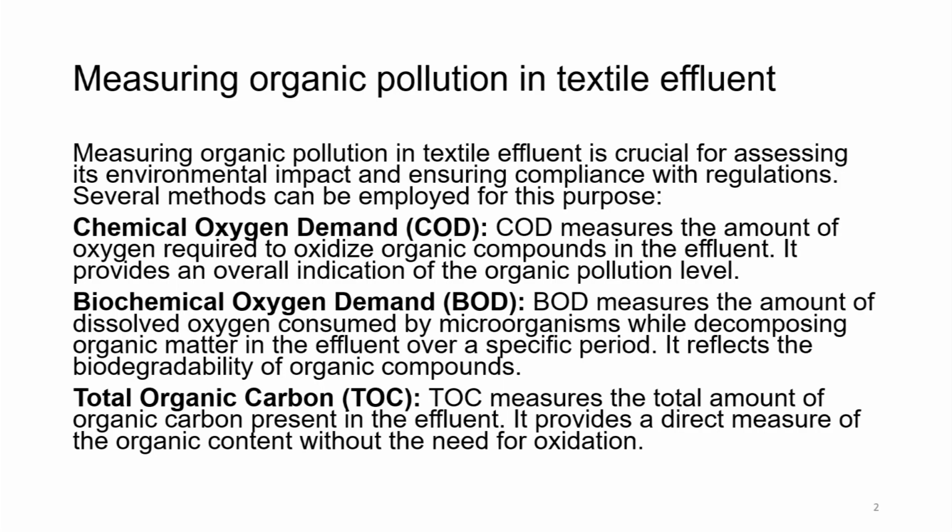BOD, biochemical oxygen demand, measures the amount of dissolved oxygen consumed by microorganisms while decomposing organic matter in the effluent over a specific period of time, which is normally either 5 days, 7 days or 20 days. It reflects the biodegradability of organic compounds. So, COD and BOD are two major crucial parameters which need to be tested.